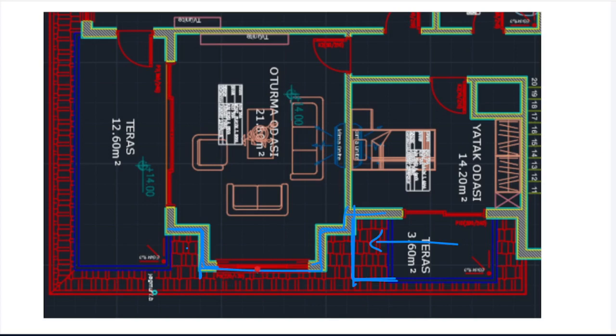Some of you will, in the project, if you are working with a gable roof, we want to see that 45-degree, let's say, if it is like that or if it is flat, it depends on you, as a dash line. So the roof plan in the duplex second floor plan, we need to see the lines, how they are working. Very light, so it will be understandable. So we will understand the overall structure. So if you are working with a duplex floor plan, please put those dashed lines in your plan.